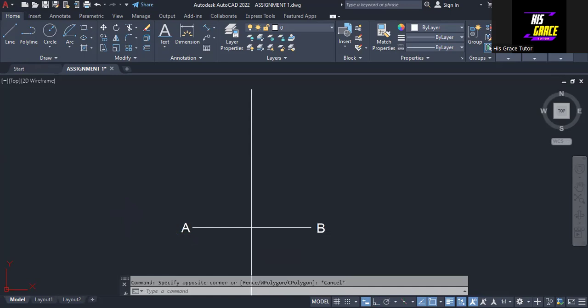Okay, so the next thing that I'm going to do now is, so we are constructing a heptagon. That's a 7-sided polygon. And before I go on to construct that heptagon, there's something I need to do. I'm going to draw a line from this point A here, and that line will be at an angle of 45 to the horizontal. If you can see on the screen, we have the angle of 45. I will drop it here like this.